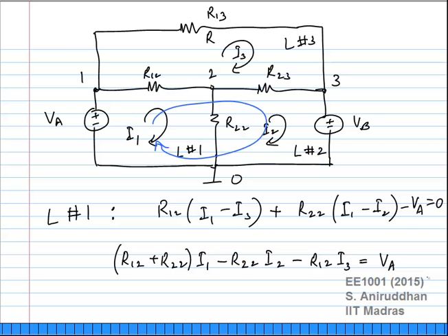In the case of the nodal analysis, that would have corresponded to writing KCL for two or more nodes put together. So there is nothing unique about this. You could have done that, as long as you ensure that you are choosing a unique set of super nodes. So that is not the difference. Any other ideas as to what could be causing this problem?